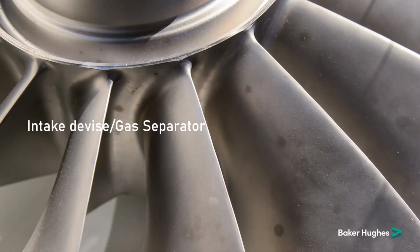Radial is utilized on low rates and when you don't have any plugging possibility, and it is also used when you need production optimization. Mixed flow is utilized when you have high gas, high sand content, possibility of plugging, and higher rates as well. In terms of construction, there are 2 categories, either floater or compression.